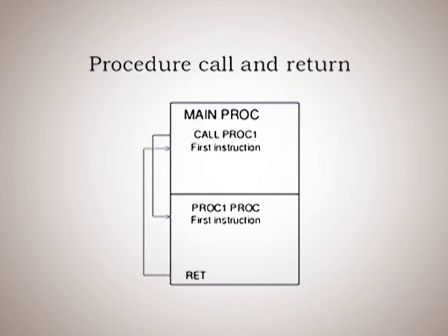The return instruction, which is written as the last statement of the subroutine, makes use of the top of the stack to return to the next statement written after the call to the subroutine. In case of an intra-segment return, only the top 2 bytes are popped from the stack and assigned to the instruction pointer.